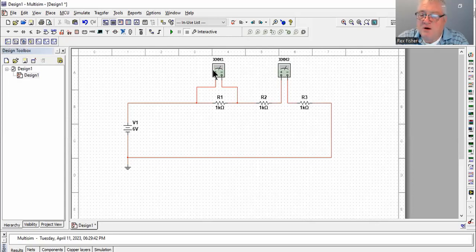Now, if the voltmeter needed to have a really high internal resistance to prevent very much current from flowing through it and changing the circuit, we want the multimeter set to measure current to have a very low internal resistance, because if it's got a significant resistance, it's like adding another resistor here, and that changes the circuit.